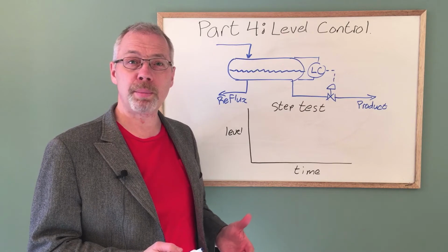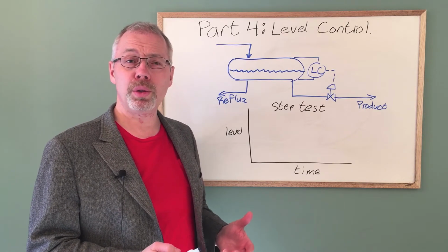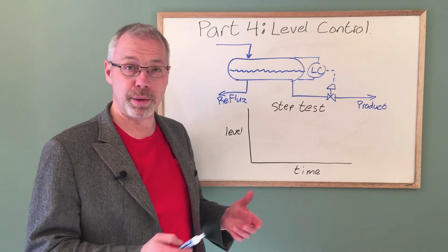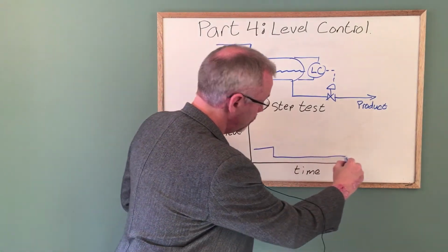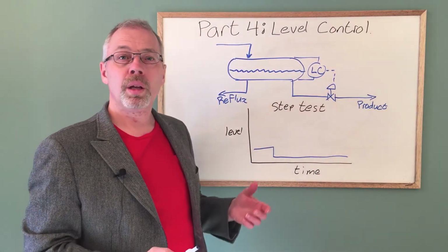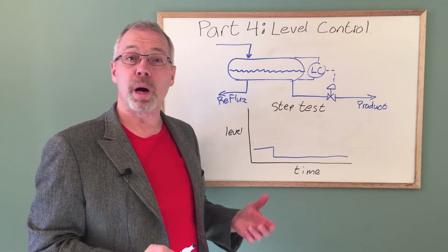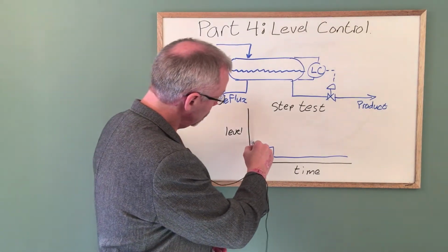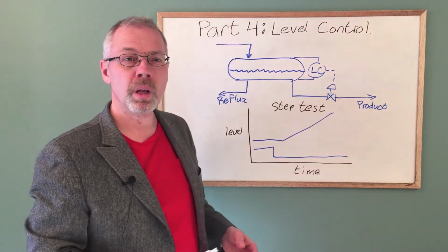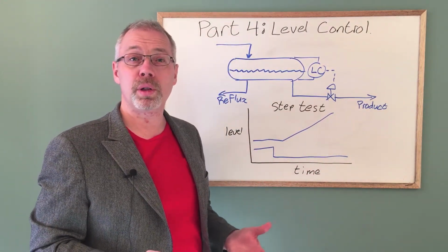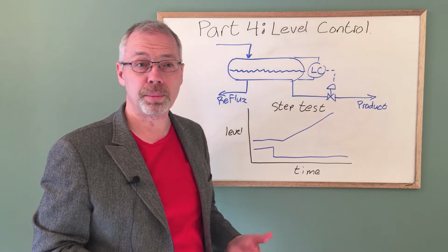Let's consider a step test on the level by closing the control valve 1%. This causes the level to ramp upwards. In our case, we will consider a time delay of 10 seconds.